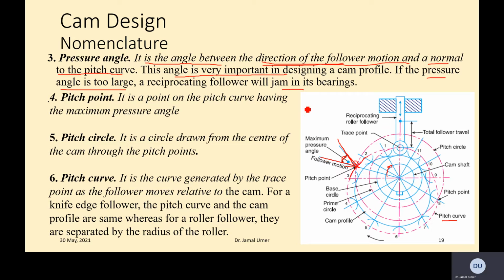For example, when the cam, the way it has been drawn here, travels from here to here, it is a slow progression upward. It is slowly going up, but the actual climbing starts from here. Now imagine if this angle is highest, really high, because we are giving quite a peaky mountain to the follower. The follower has to do a lot of work to climb up this cam profile.